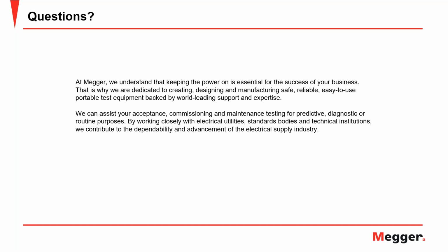When we talk about power factor or the capacitance value going down, I will cover the power factor values first. When you talk about power factor values going down, I want to highlight that insulation cannot improve by itself unless you do some oil processing or something like that. Then yes, power factor values would improve. But if you have not done any of those things, then the power factor value cannot improve by itself, because insulation cannot improve by itself.